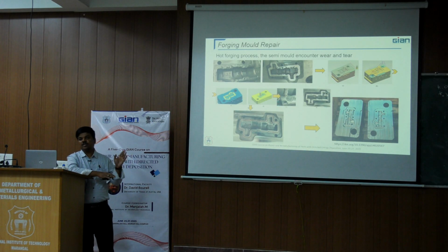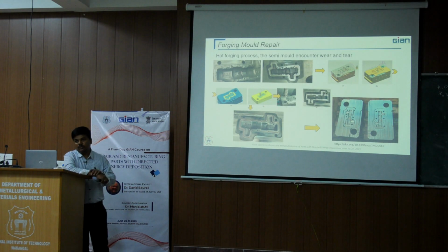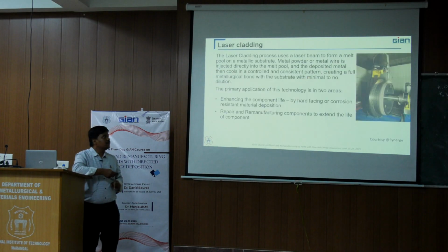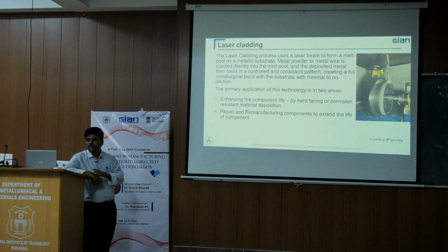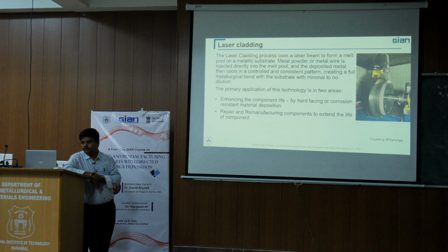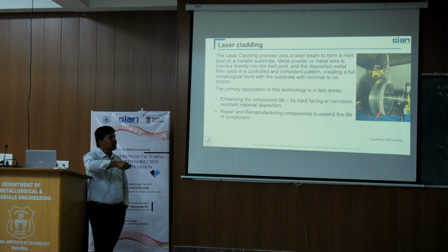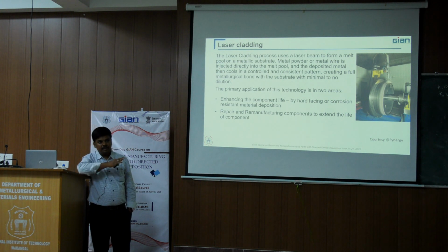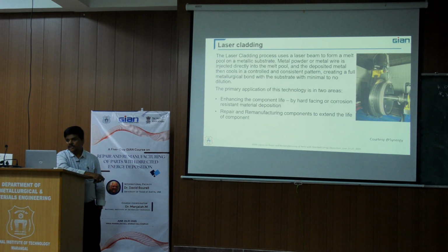That is where repairing is very beneficial with the laser DED process. With other technologies, repairing these parts is very challenging and we have to throw them away. Apart from repairing, we can also use it for laser cladding. If some part is worn out, or if I want to improve its performance or its corrosion properties by hard facing, I can add additional corrosion resistant materials, or wear resistant materials, by laser cladding. It is the same laser direct deposition process, but with additional materials added to improve performance.